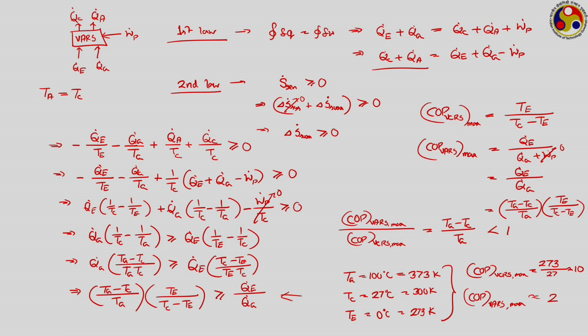So, the absorption system, despite having a very small work input requirement, is not going to give a very high COP. Only if you have a source available of a very large quantity of thermal energy does the absorption system become very productive, because then we can use the waste energy and run the system almost without any mechanical energy input. In that case only the absorption system is economical, and that is why we generally use the absorption system for large scale applications with some source of low cost, large quantity waste heat, or maybe just renewable energy sources like solar energy.